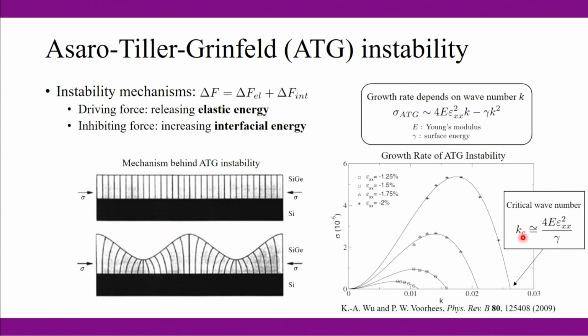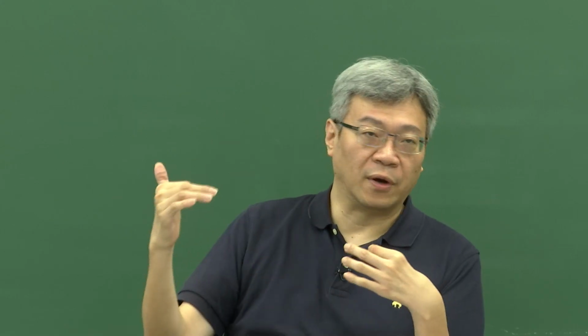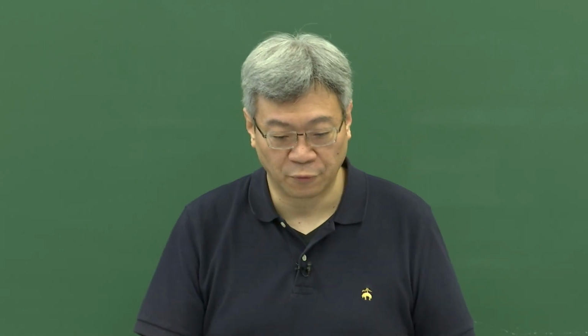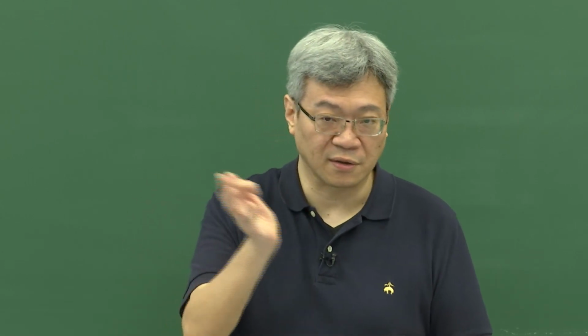All right, so now let me introduce what the simulation parameters are for this solid-solid simulation. We're trying to have a rather mobile grain boundary, which means we don't want to choose our parameters really deep inside the solid region. So we choose the parameters rather close to the solidus line.